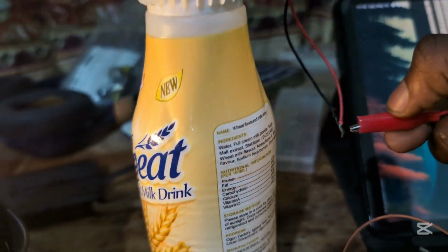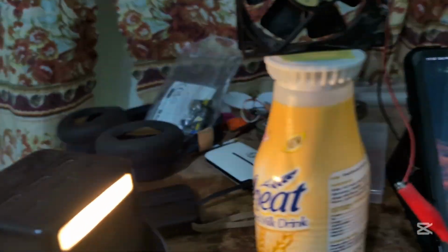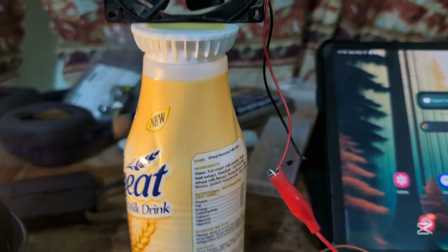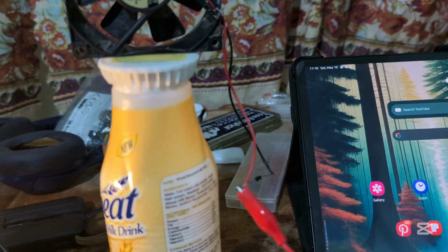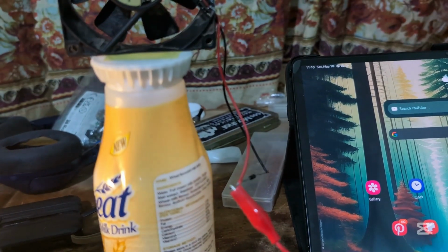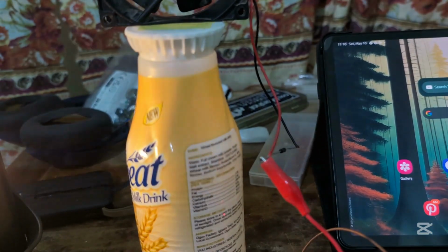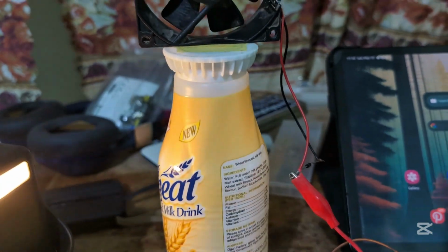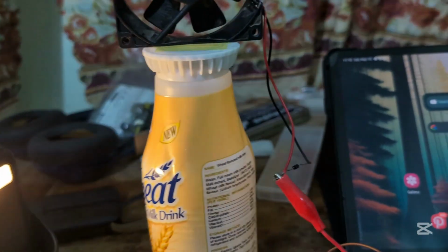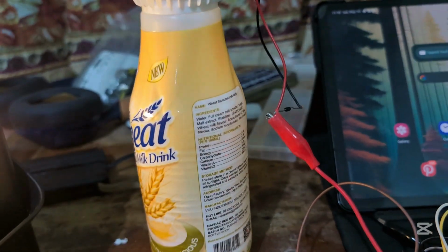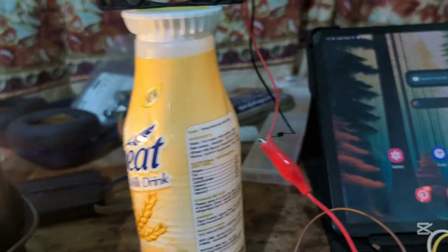positive to positive. As I earlier explained, I have a diode there that serves as flyback protection. Inductive loads like this have coils, so when the coils stop, they send a very huge inrush voltage, called a voltage spike, and if not careful, that voltage spike can flow back into the whole circuit and damage some devices over here. That's why it's always advisable to use a diode across the terminals of your load. It serves as a flow back into the fan that we are controlling.